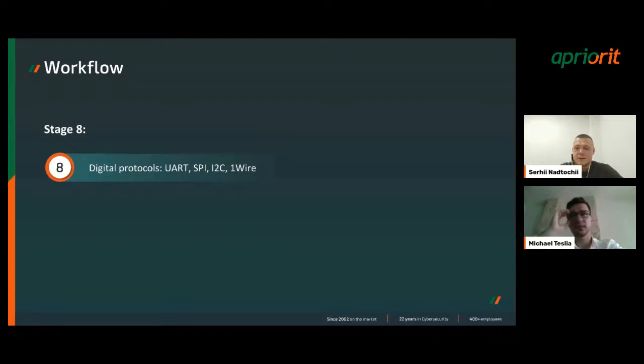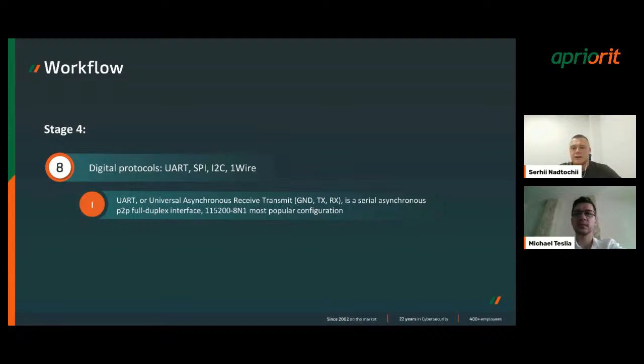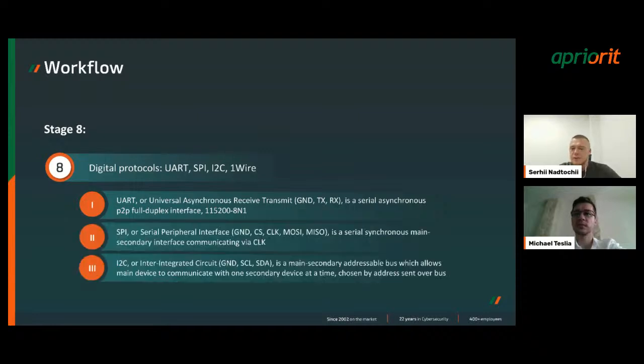The next one, the digital protocols. It is also good to know about them, at least some basics like we have UART, SPI, I2C, also sometimes one wire. Maybe the most common are the serial interfaces, which are used for some internal and sometimes for external communication between devices. So we will go shortly just to understand what the difference is.